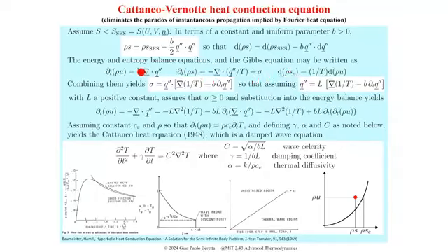so if you do this substitution, you can obtain the expression for the entropy production, which is the product of the heat flux, times this thing. So not only the gradient in 1 over T, but there is also Q dot, times the derivative with respect to T of Q, which comes from here. So this term in square brackets is now the affinity. The expression for the affinity has changed.